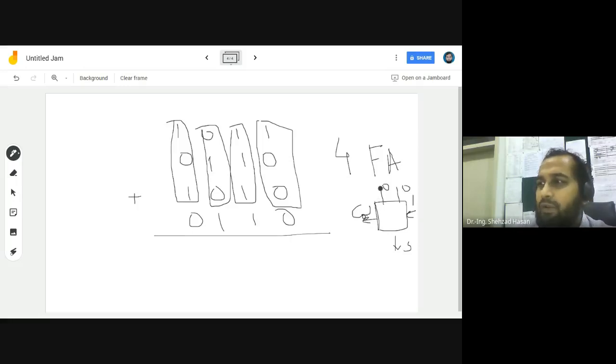The thing is that you have three inputs in a full adder. You can give any input to any side, so that's not a problem. This full adder is going to give you a result. It doesn't matter if there is a one over here or here or here, as long as there is a single one. It's going to give two outputs, a sum and a carry out. Now one output, the sum, which would be one in this case, is going to go on this level, and the carry out, which would be zero in this case, is going to go on this level.